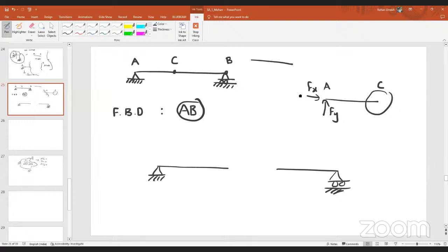These are called the resisting forces because of the supports. And wherever you are breaking in between a surface, not only here, you break any surface, you have to represent the contact forces at that point. Here, again, I'm telling you, it is a 2D problem. So how many contact forces may exist? Again, the answer is 3, always 3. Even if I talk about deflection, 3. If I talk about contact force, also 3.